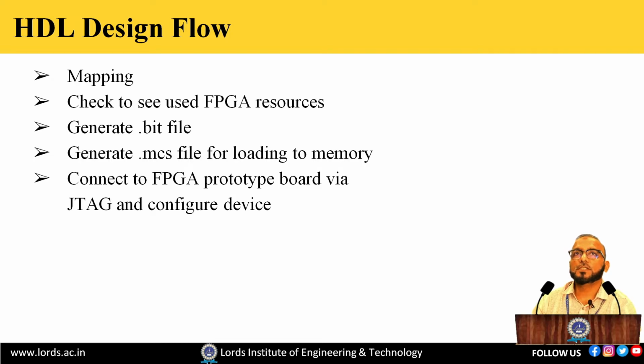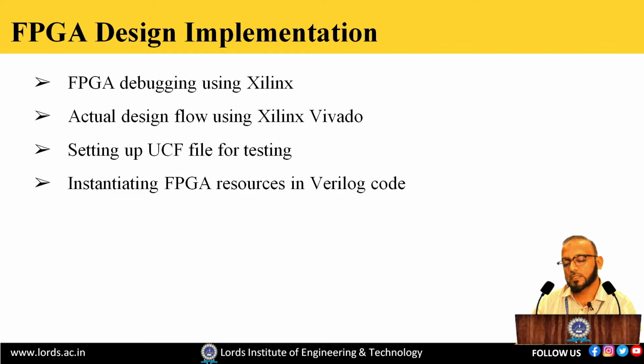FPGA design implementation, after debugging using Xilinx. I'm saying Xilinx because it is the most common, not open source, but readily available to engineers. Let's say the license-free version of Vivado, which you can use to make a design. Set the user constraints file, that is the UCF, which is what is actually required for testing. And instantiate the FPGA resources in Verilog.